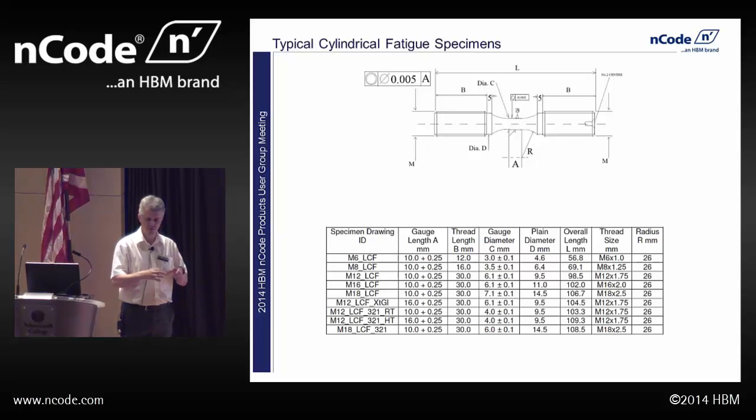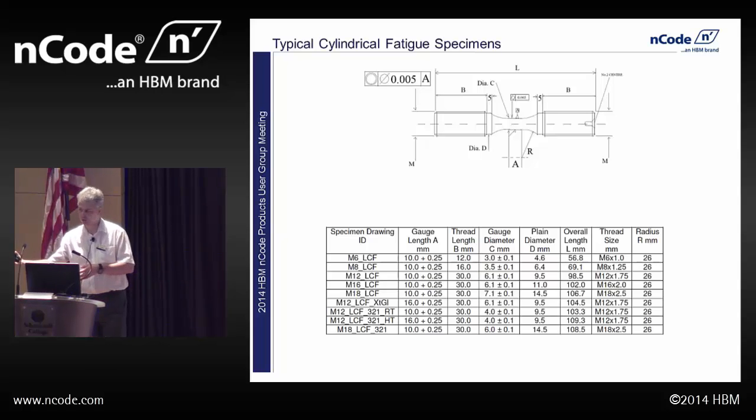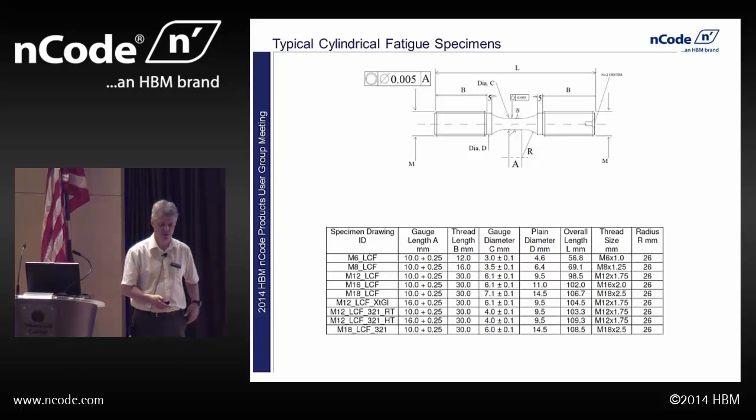Also with sheet specimens, you've got to be a bit careful with the edges: break the edges and clear those off. And in terms of surface finish, generally for most materials you do this in polished form, so not mirror polish, but all the machining marks removed. So for a baseline material sample, a polished specimen gives you the best fatigue performance, with no effective surface effects. You then might want to do samples at your surface finish. You can either take account of that in the software or in the materials data. So if you want to be really accurate and you generate the same surface finish on your components all the time, you can use samples with that surface finish to get you more accurate data.